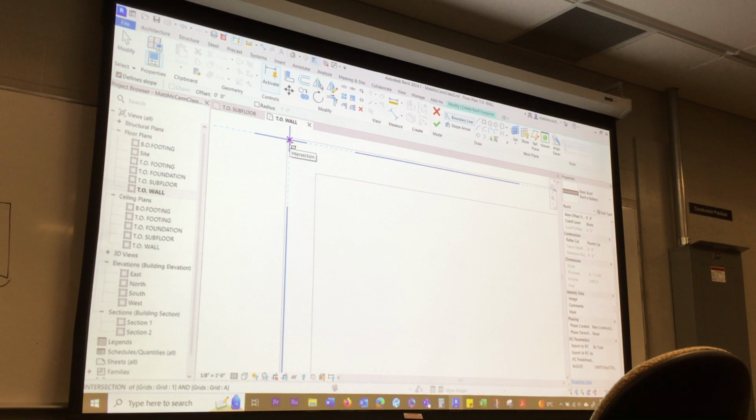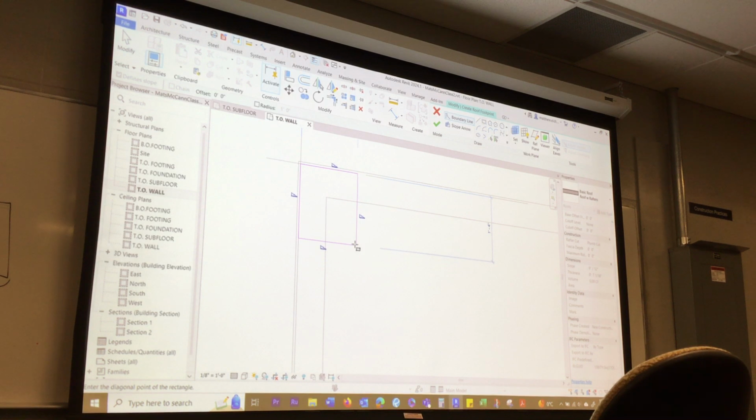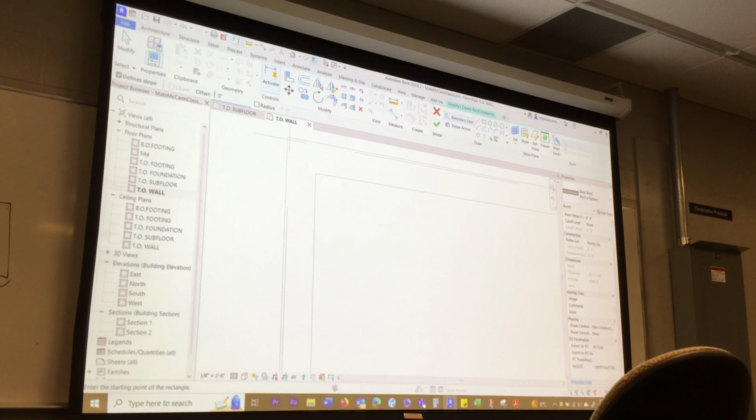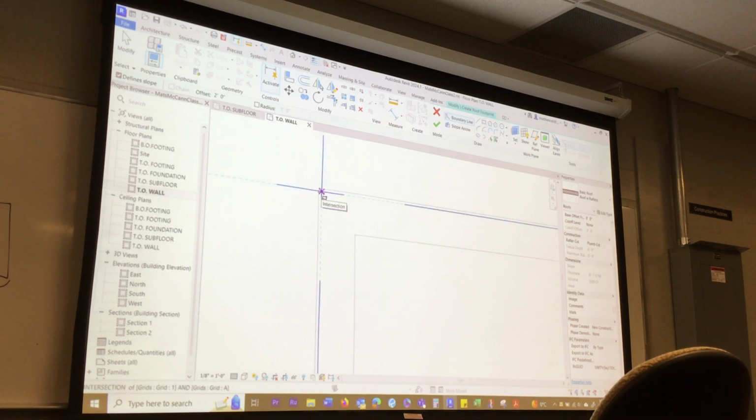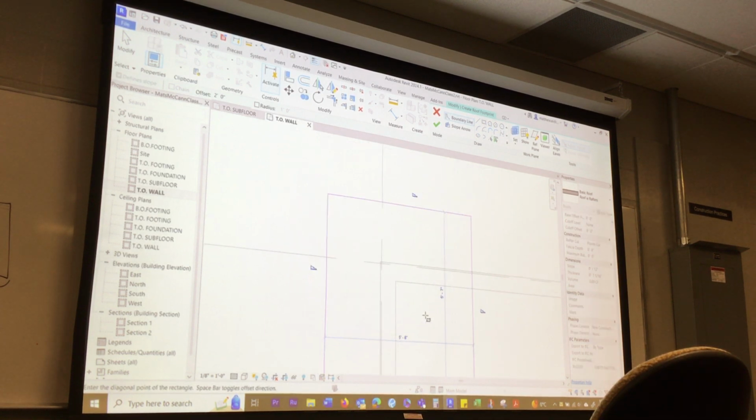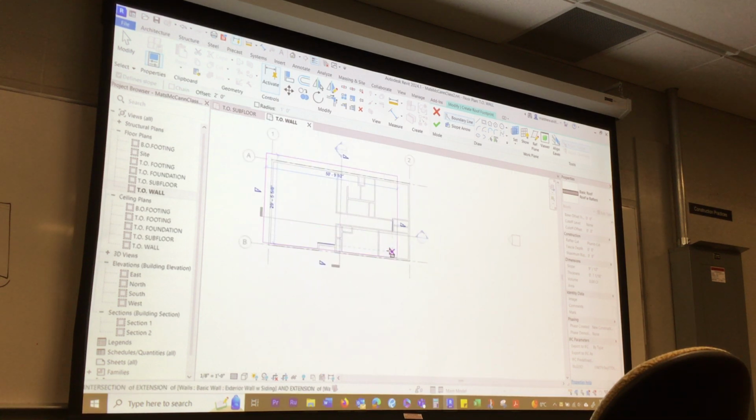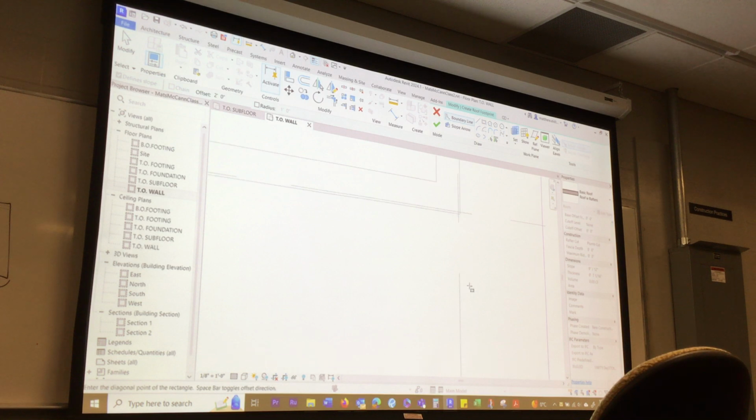If you don't see that, it means you probably don't have fine turned on. I'm gonna grab it and I'm gonna start to pull. Oh, I gotta leave because I lost my offset. It's easy to do. I lost it just by grabbing the tool. No, it's okay now. Okay, so start there, you can see I've got an offset going on there. It's drawing the triangle bigger than the house is, which is what I want. You can also see I've got slope indicators on there. And just go right across and land it right on the outside of your sheeting.